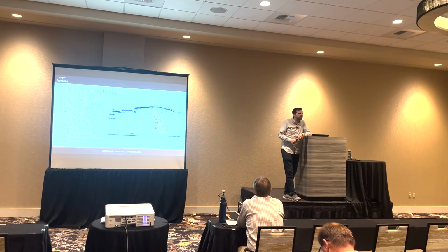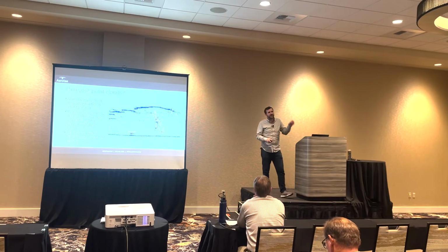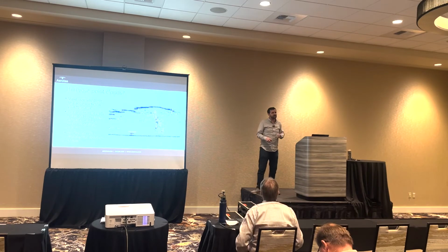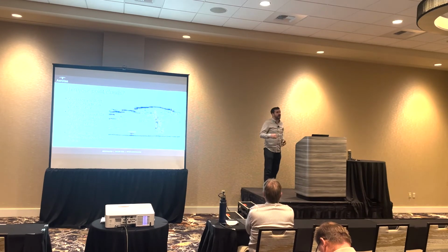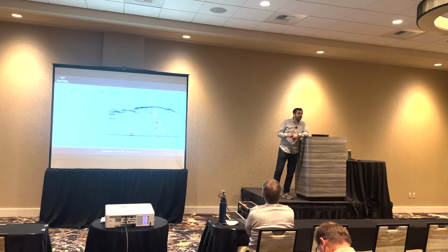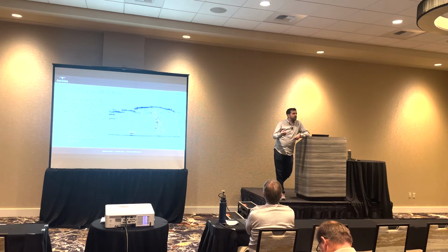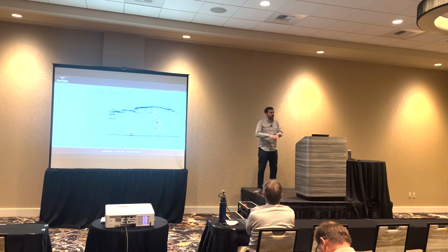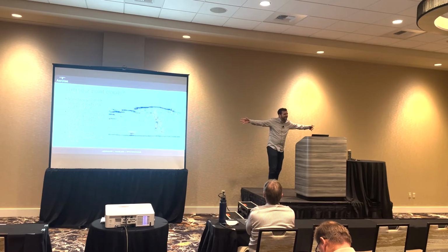None of them. What is the difference in behavior in the software when you classify terrestrial LiDAR versus photogrammetric point clouds? So terrestrial LiDAR, aerial LiDAR, and photogrammetric point clouds all have extraordinarily different behavior when you're running a lot of these algorithms and procedures, especially when you have LiDAR with multiple point returns, right, when it's going through vegetation. When everything's pointing down, you can have a very high confidence that the last return is going to be ground. Whereas if you are doing terrestrial LiDAR and it's going from the side, that last return going from vegetation is likely to be the facade of a building.